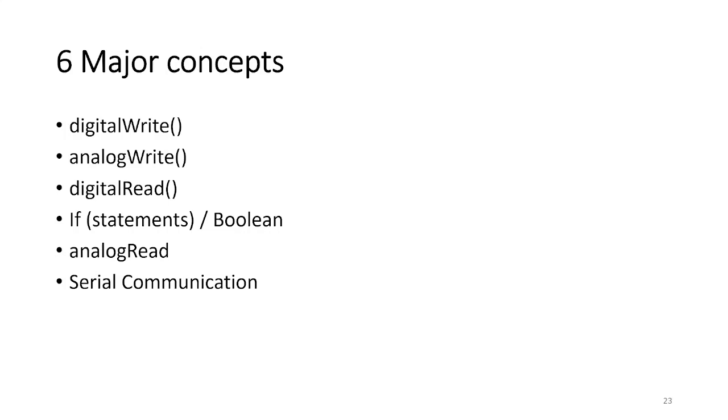But you can also define your own using the SoftwareSerial library, and for that there's one condition. You need to make sure the pins you are defining as TX and RX are PWM. PWM means pulse width modulation.